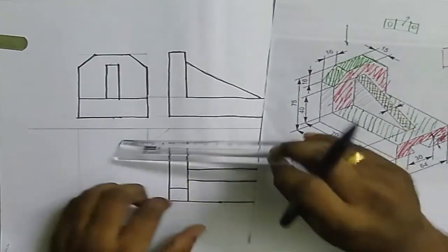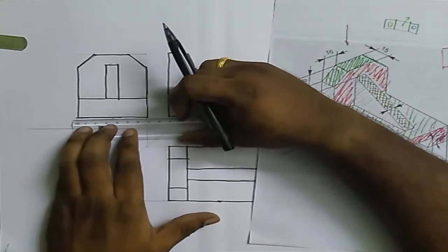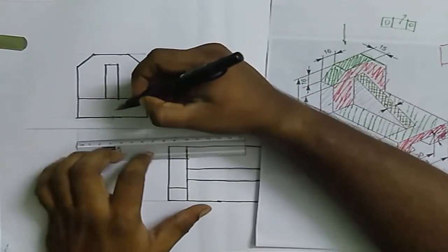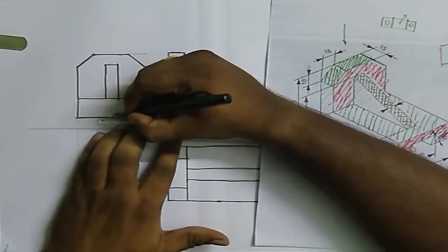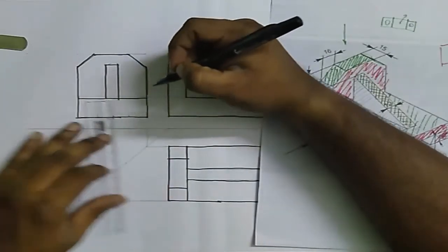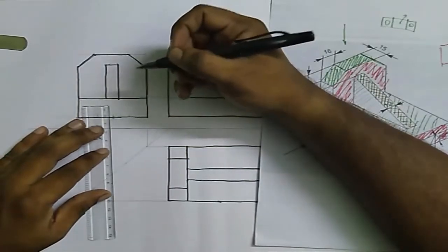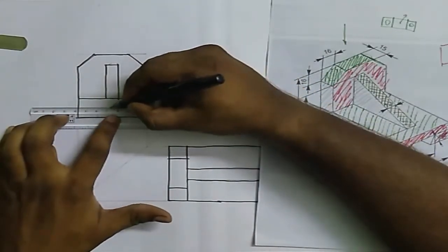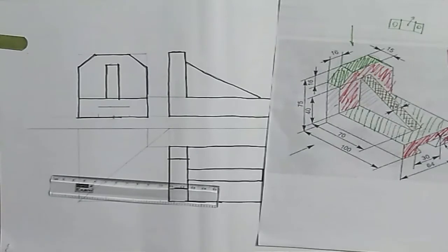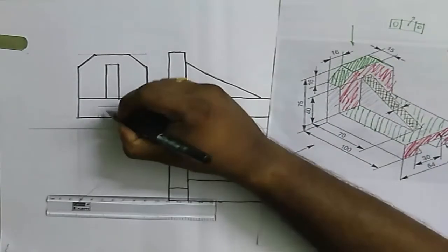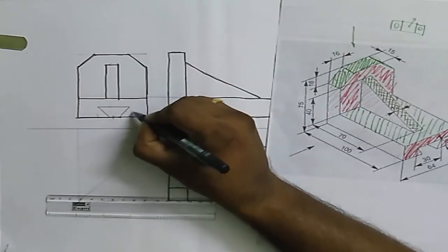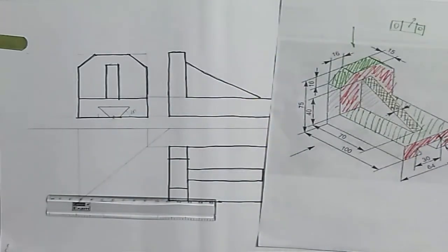So what you have to do is just mark the center point of this 64 mm, that is 32 mm here. From 32 mm you just measure 15 mm in this direction and also 15 mm from this direction. Then mark the height. The height given is 12 mm. So here 12 mm. So draw a horizontal line like this. Then rotate your drafter to a 60 degree, draw a line like this so that this angle will be 60 degree. So this is your final drawing.